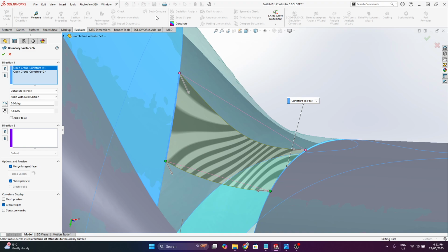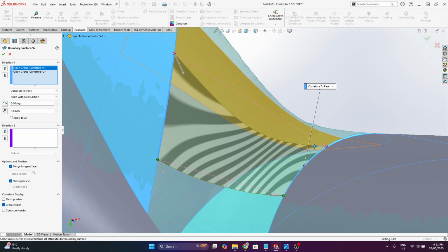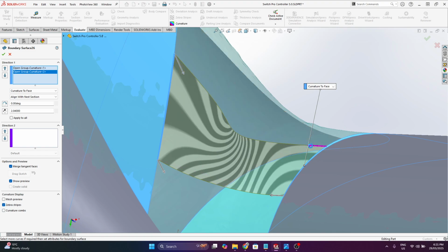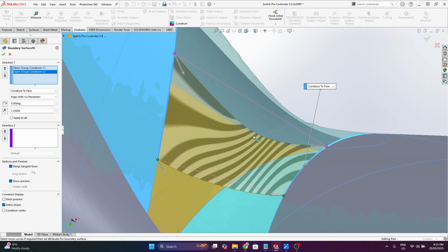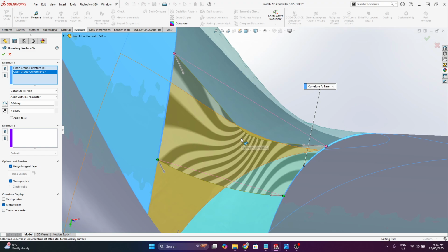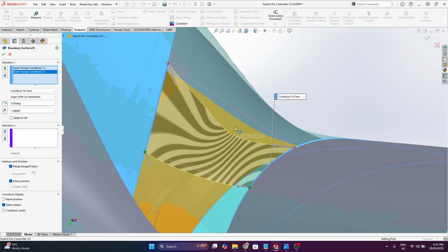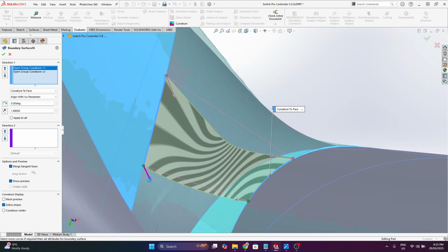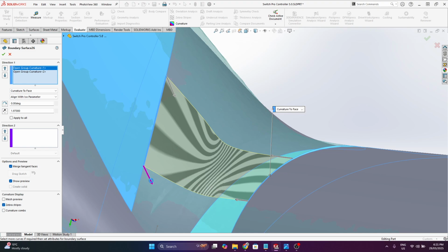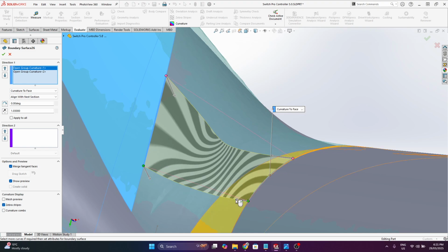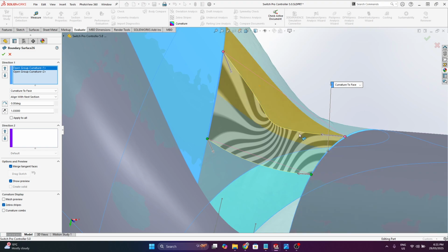It's useful, or maybe even crucial, to have the zebra stripes turned on when you're doing this to see how the curvature is changing. Obviously, zebra stripes that get squished together more or less represent tighter curvature in that region, and then moving around, manipulating the view. That becomes a little bit tedious and almost artistic at this point.